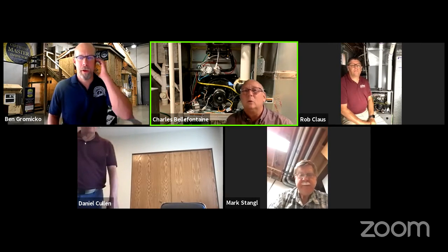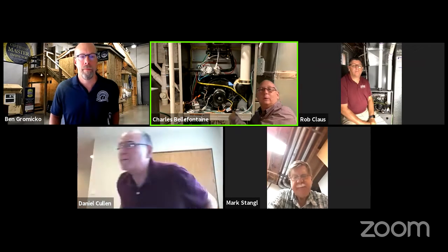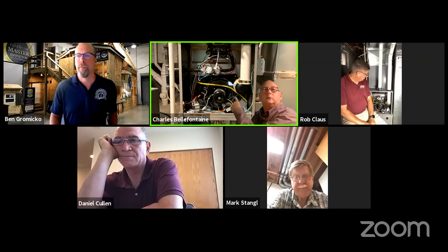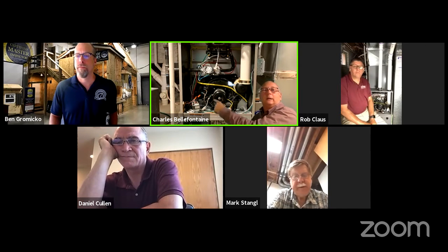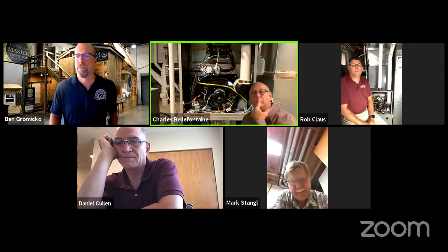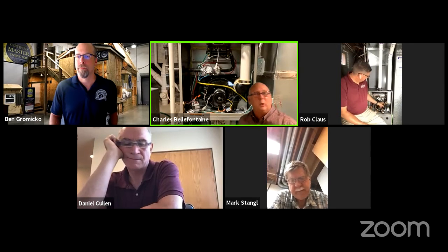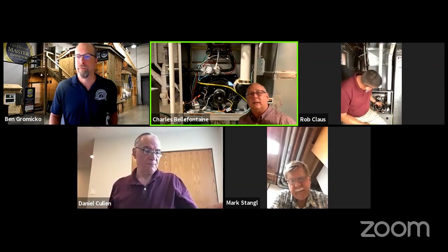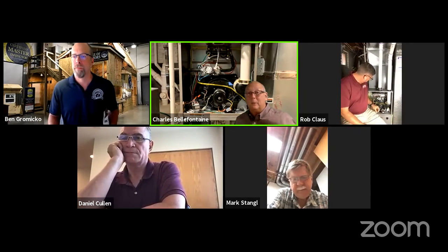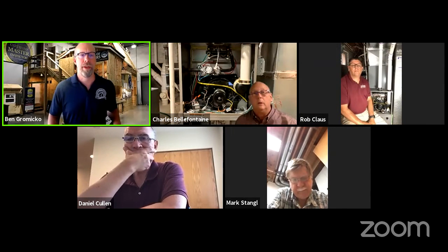One more thing too: on the bottom of the floor is where my condensate collector is, right underneath here. That yellow hose that you see going across is collecting condensation from the secondary heat exchanger. That's also pouring into there, and then that goes to a floor drain. It's not customary here in Chicago that we put any neutralizers or anything like that. We just send everything straight into it. I don't know if that's customary in other parts of the country, but not here. That's pretty common, not to neutralize it.